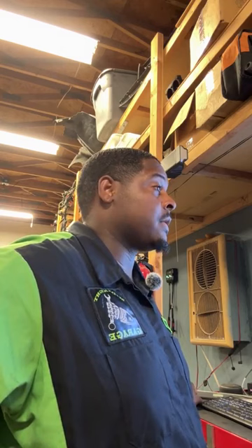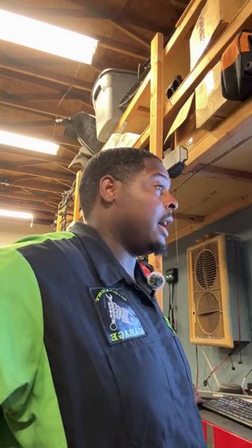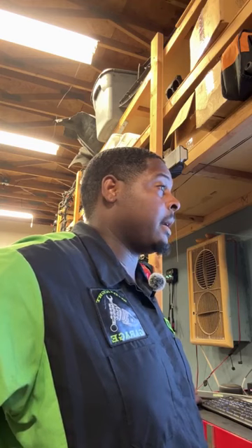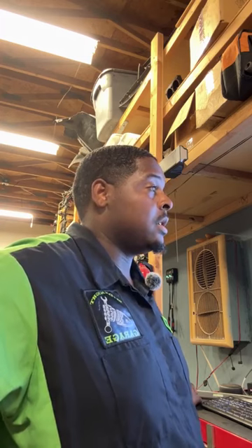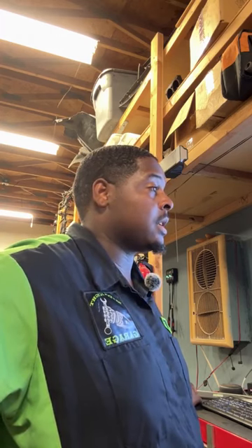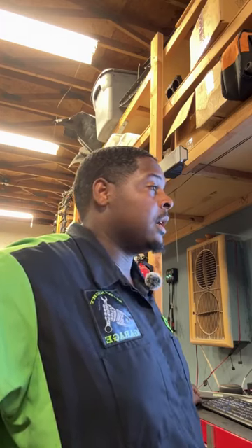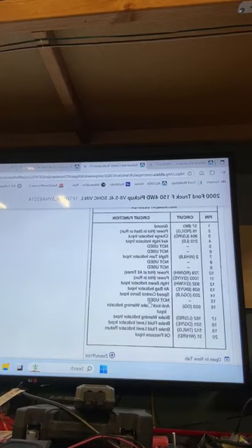So what was that on? Diagrams. We're going to look at connector views and airflow meter, clutch control assembly, cruise control servo, engine computer, come on, instrument cluster. There we go. Instrument panel gauges and warning indicators. So let's see if that helps us. I'm going to turn you so you can see. So, instrument cluster pinout. Here we go. We've got the ground, charge indicator, right turn, power, high beam, airbag, speed control servo input.